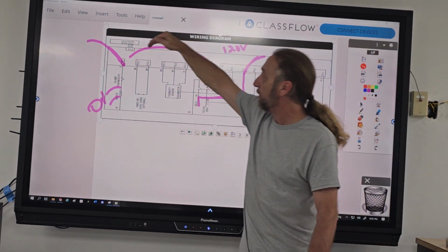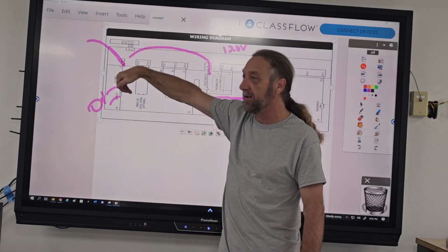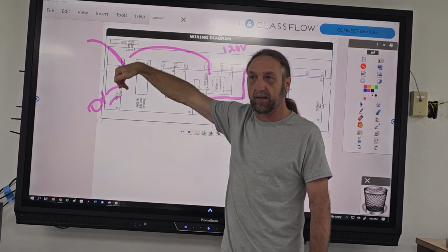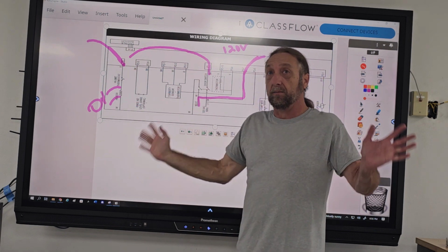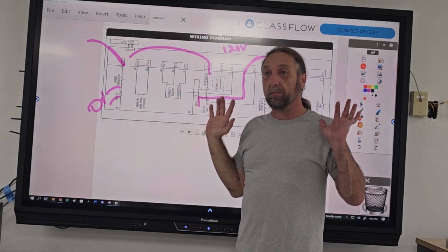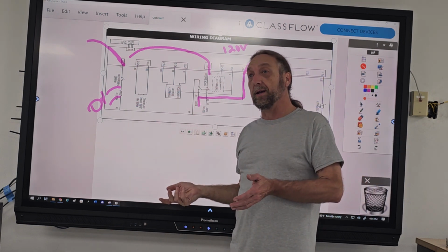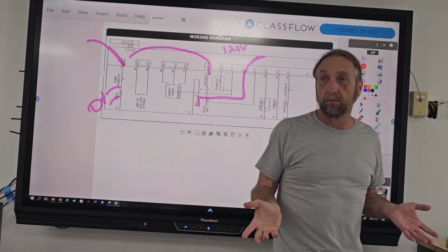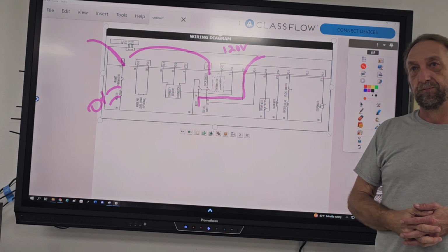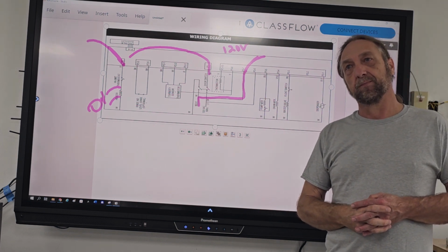It was coming out the board, but never made it to my heater. What's in between is that thermistor or thermostat, and I change it, and I'm done. I found my problem. Now, if I wanted, I could take a test cord, put it on the heater and see if the heater got hot, right? Right. That's true.